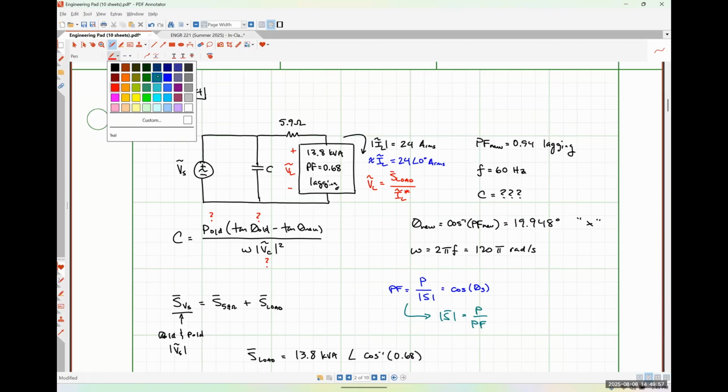And then I can use the information that was provided to me to give me the voltage drop across my resistor. And then I could use Kirchhoff's voltage law around that path to find Vs, under the assumption that we started with a current phase angle of 0, and then I could just take the magnitude of that voltage. That is perfectly okay. And to me, it's actually the more obvious route, but there is a different way that we can do it.